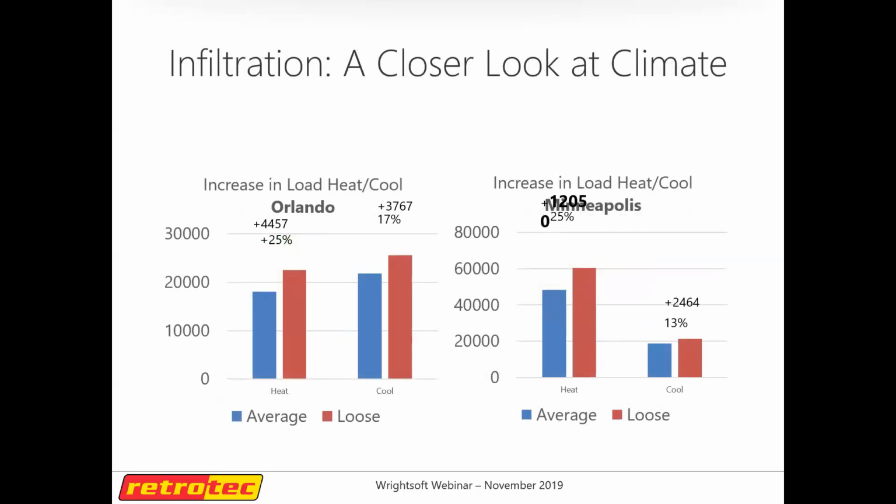But in terms of maintaining comfort, it is simply put easier to heat than it is to cool. Because when you're cooling, you're actually doing two things. You're controlling temperature and you're controlling moisture. And you're controlling these two things when the magic box on the wall only measures temperature. So you have to dial the system in so close that it runs as much of the time as it can so that it can do its second job, which is moisture removal. So that's why sizing is such an important issue.